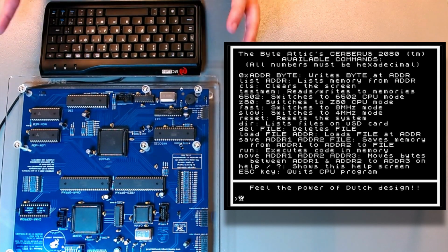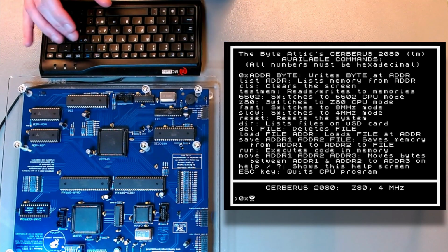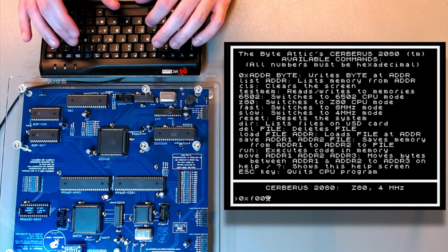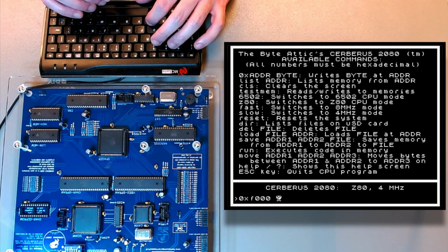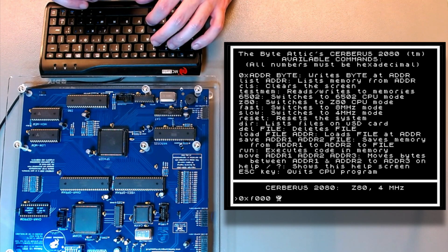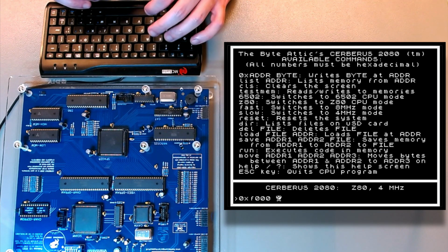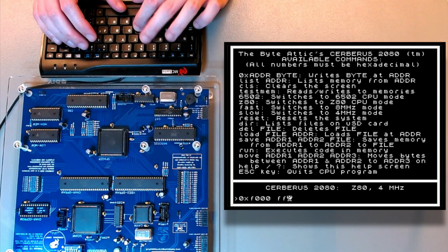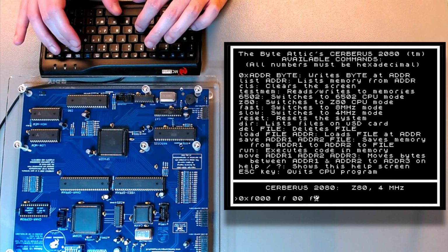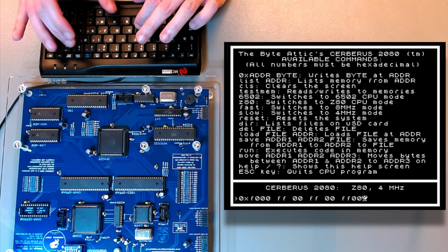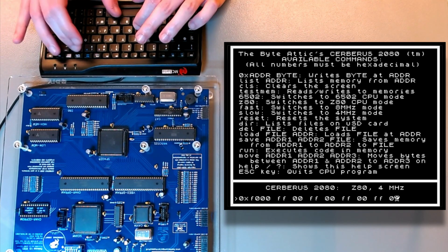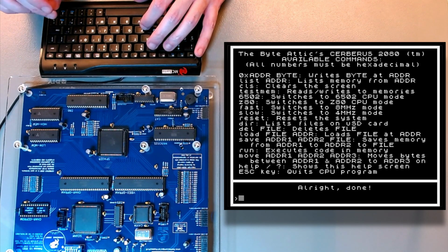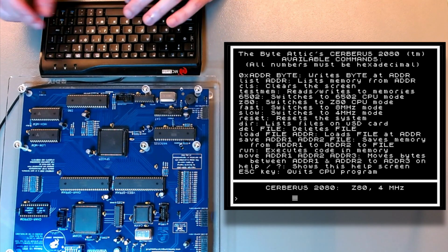Actually, I can write to any part of memory directly by typing 0x and then the address. Now let's see, starting at F00, that's the character definitions. And the first character definition is the cursor, the little strong man with a C on his chest. So I can change that one. Let's replace it with alternating lines. FF00, FF00, FF00. And you see that the cursor character will change into 4 horizontal lines. There you are. That's the new cursor.